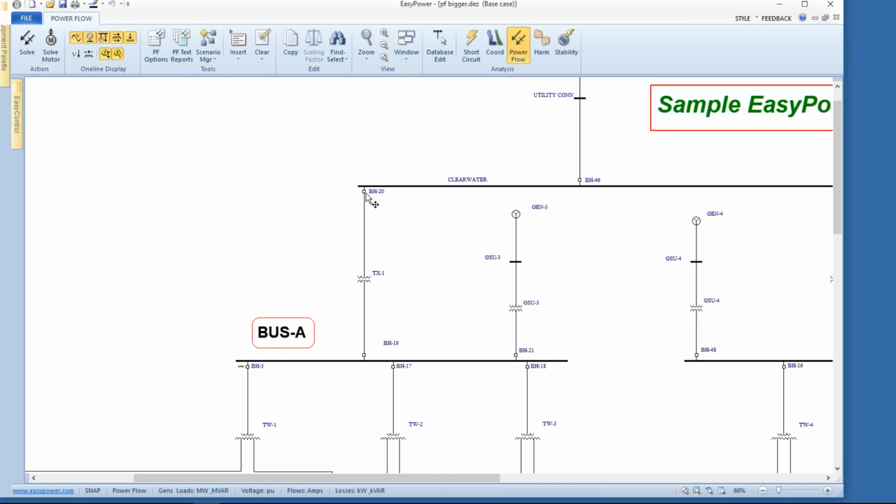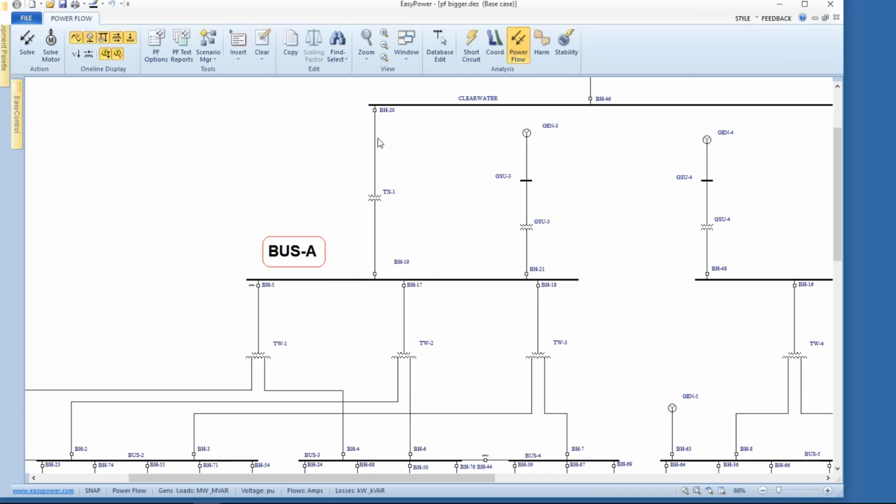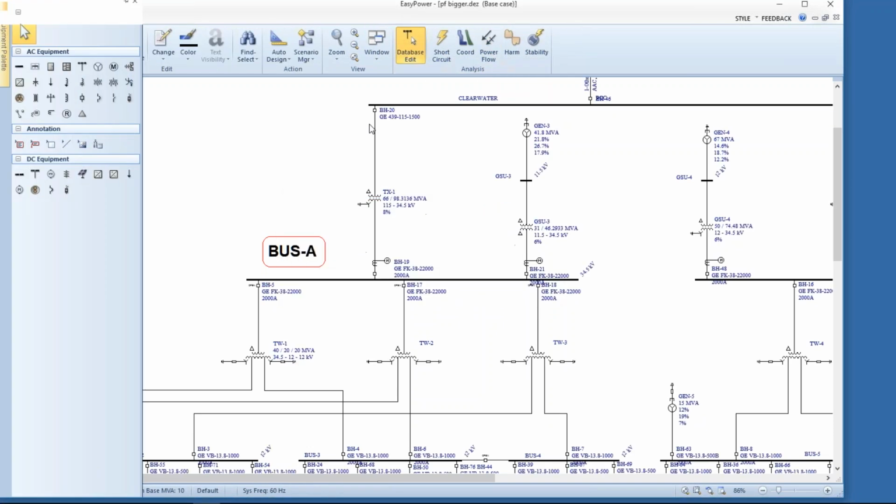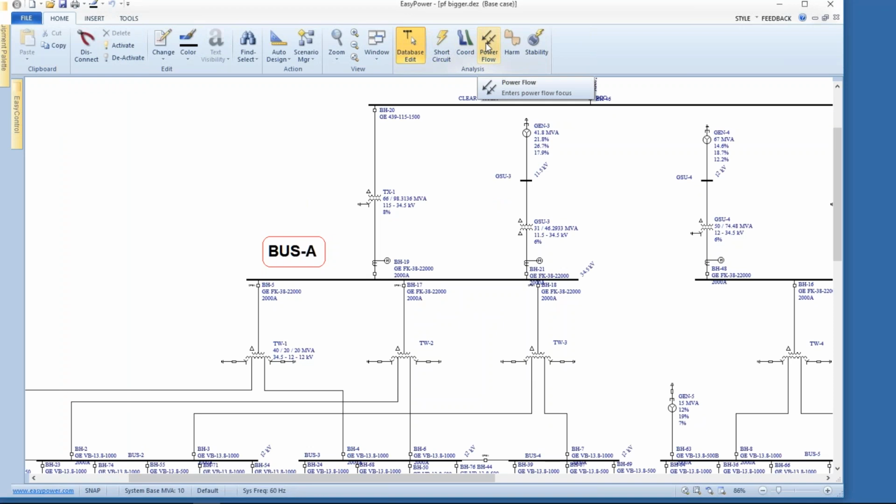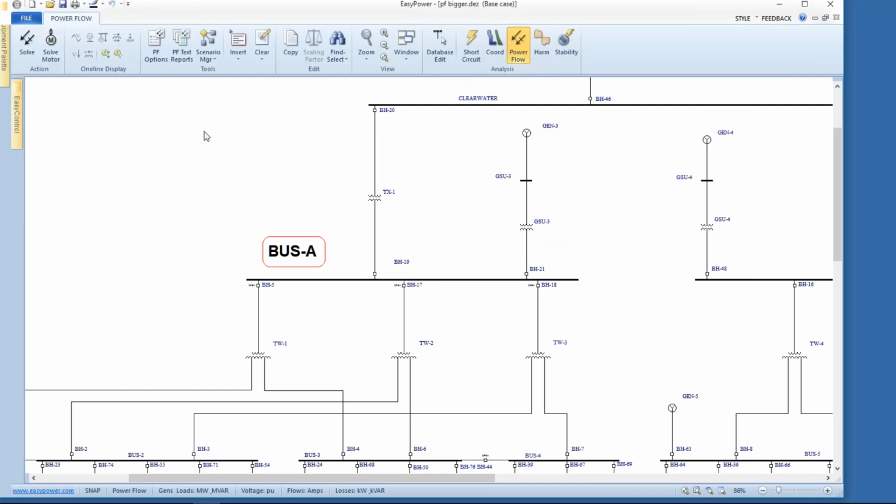And personally, I like to follow the same kind of mentality or progression, and that is, okay, if I follow this load downstream, I'm going to go ahead and open these 3 breakers. I'm going to go back to database edit. After we get a couple rounds of errors, I start to get my PowerFlow faults starting to stack up. So I'm going to re-enter, solve the equations, and again I don't have any errors as long as I have the loads on this bus isolated.